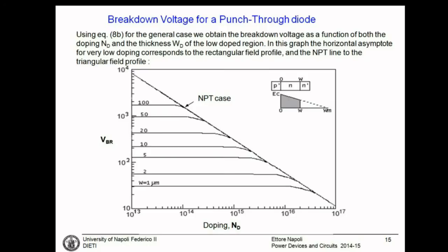In the end, we will have two values that we need to set to obtain the breakdown voltage: the thickness and the doping. And there are two design options: punch-through and non-punch-through diode. Punch-through and non-punch-through device, this will be valid also for MOSFET, IGBTs, and other devices. The total design plane is shown here in this famous plot that is probably directly taken from the Baliga book.